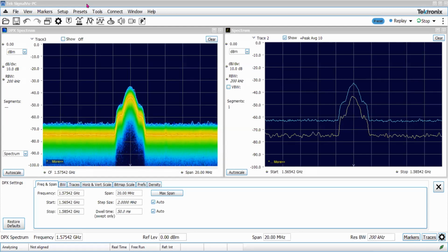You cannot transmit in the air, otherwise it will interfere with nearby devices. So you have to be very careful when you do this type of test. You have to connect from the cable of your transmitter to the device. And now I am sending the signal here. This is how, if you look at the satellite antenna, the signal will look like.